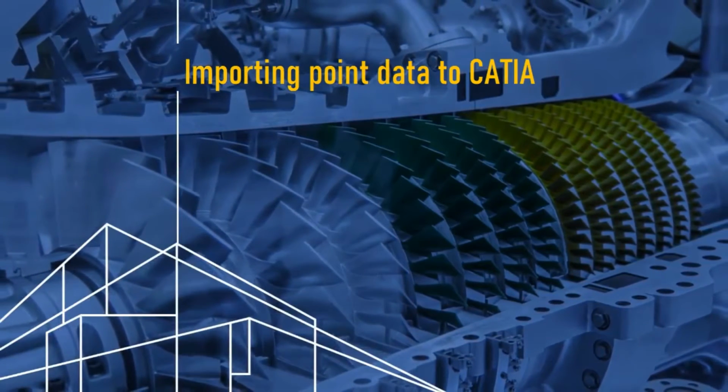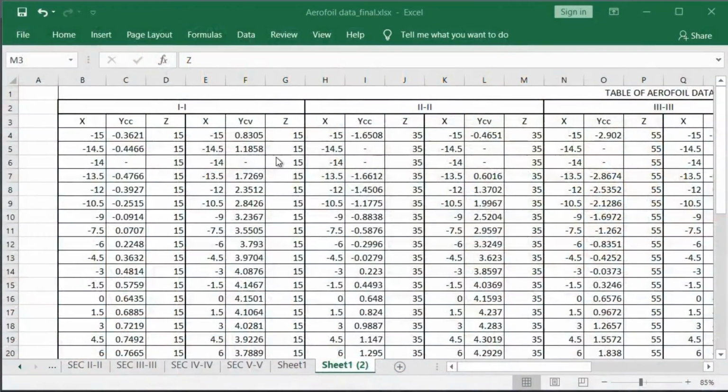In the last lecture, we had created this Excel file. But this Excel file we cannot import into CATIA. We have to convert it into an Excel macro file, which is by default given in CATIA. You have to find it in the CATIA installation directory.